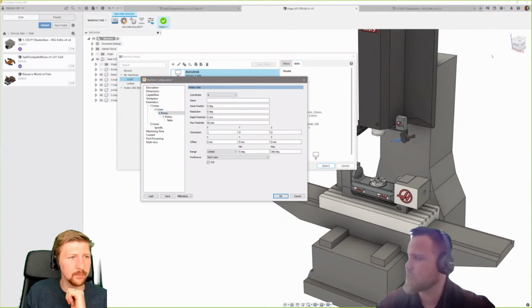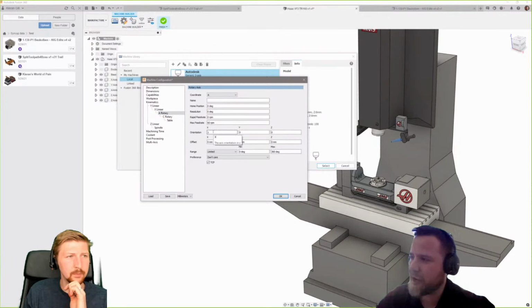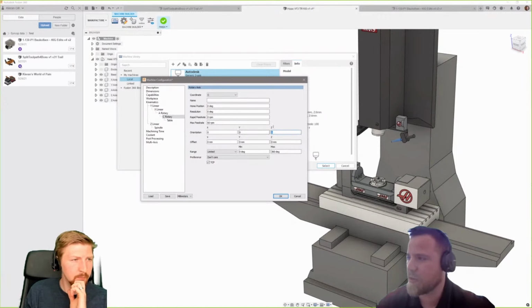So the A-axis is really rotating along the X direction. And because it's doing that unit vector, we place a 1 in the X column. Now the C, if we have a look at the C, the table itself, this rotates indefinitely through 360 degrees, and it rotates around the Z axis. Hence why there's a 1 in the Z column. Cool. So we've sorted the orientation. Let's just quickly go back to the axis and define the range.